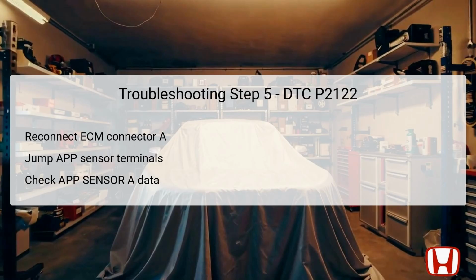First, reconnect the ECM connector A, 49P that was previously disconnected. Next, with the sensor still disconnected, create a jumper connection between terminals A, APP sensor 6P number 4, yellow wire, and B, APP sensor 6P number 6, brown wire. After establishing this jumper connection, turn the ignition switch to the on position once again. Utilize the HDS to check the APP sensor A data in the system.